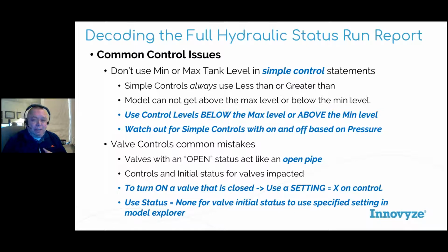I think the only place where that can work is in a rule-based control, because those have greater than or equal to as an option. Then it could do it, even though I would generally not recommend using your minimum or maximum levels for control levels because of the pipes closing. So just watch out for that. That's a very common thing we'll see a lot.